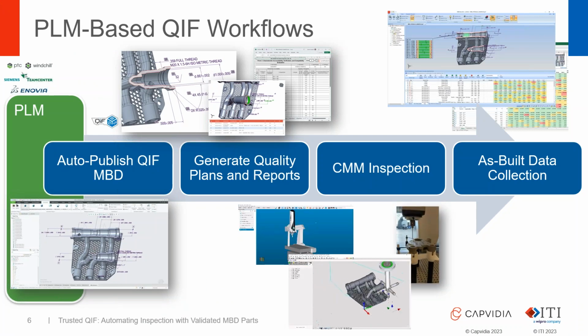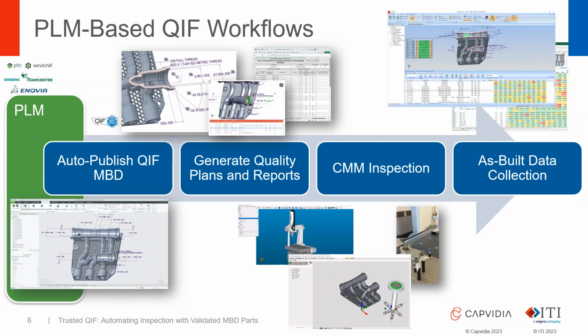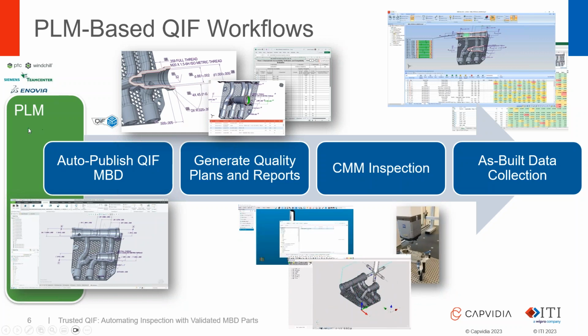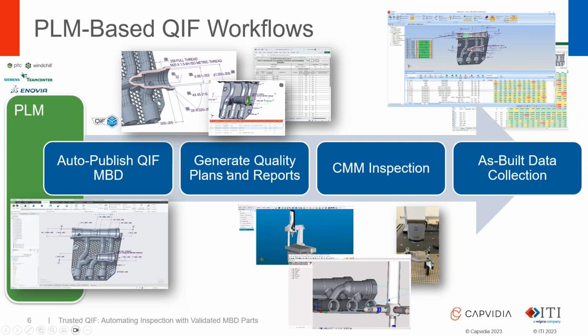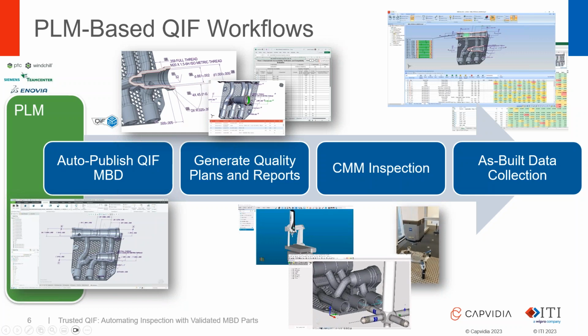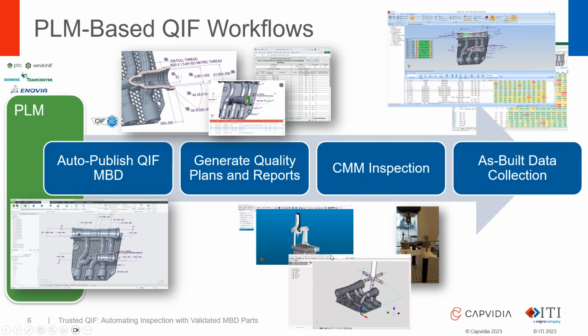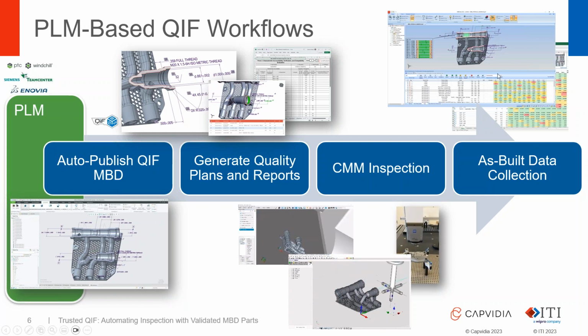I mean, this is really how you start to build it up, is with MBD, with standards like QIF. So again, what we were looking at, we started off with the PLM-based QIF model, generate the quality reports, generate the 3D HTML report, do the ballooning of the model, carry out some CMM inspection, and then finally gather that information back into QIF in a digital format.